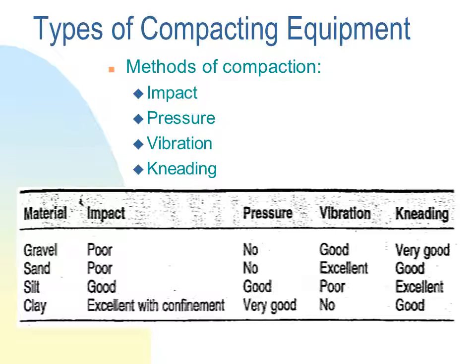However, cohesive soils like silt and clay are the opposite. If you use vibration in such a case, you will find a process called liquefaction. Soil will start acting as a liquid if you vibrate. However, impact and static pressure are more applicable in such cases.